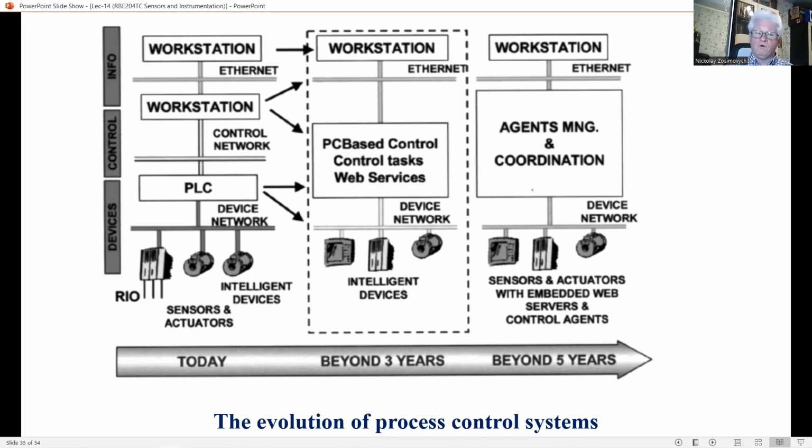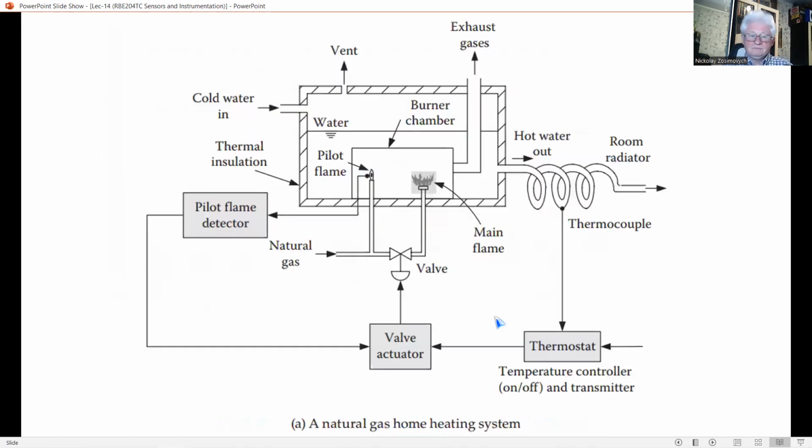The reason for calling this method feed-forward control comes from the fact that the associated measurement and control both take place in the forward part of the control system. But note, in some types of feed-forward control, the input signal is generated by using a model of the plant and may not involve sensing.